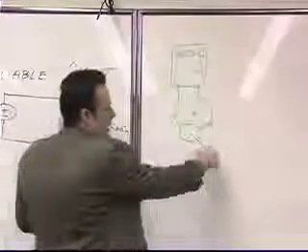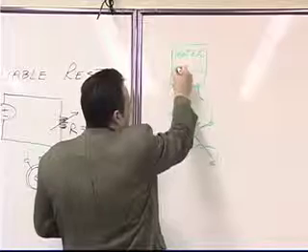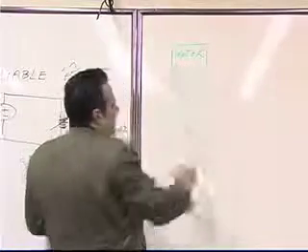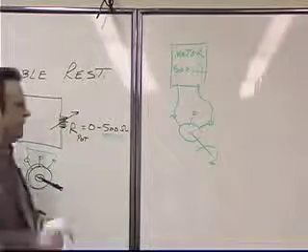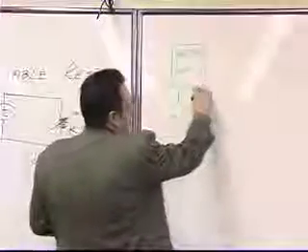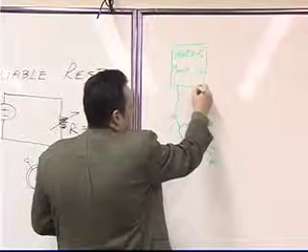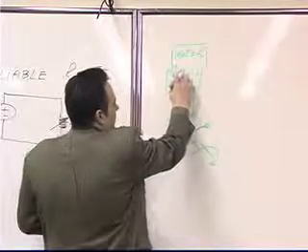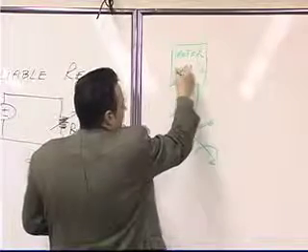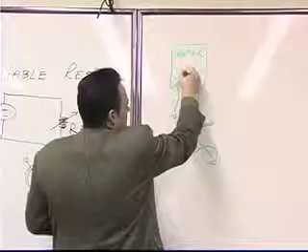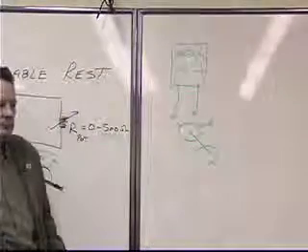and you turn the knob. The value of ohms will not change. It will be its maximum. If, on the other hand, you take your meter and you connect it here, then as you turn the knob on the potentiometer, this thing will change. 42, 47, 80, 100, whatever.